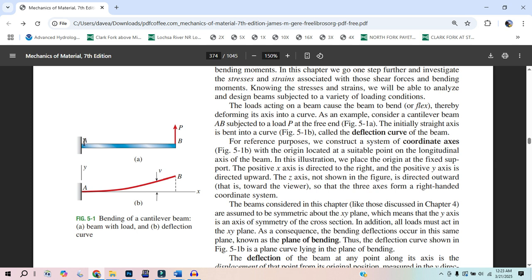Maybe it's a strong enough steel where it actually holds. But that's a hell of a lot of force in shear right there. When it comes to these loads on these beams, that's 29,000 pounds. What were we talking about? 58,000 pounds. In shear we were talking about 29,000. So let's keep that number in mind, because things are half as strong in shear, basically.